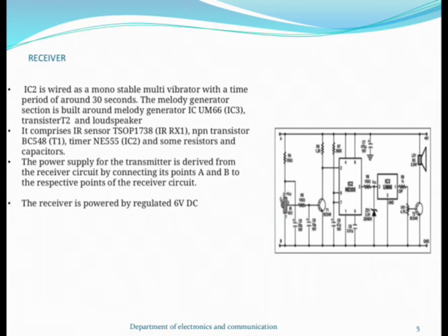Receiver. Another main role of an electronic watchdog is being performed by the receiver. IC2 is wired as a monostable multivibrator with a time period of around 30 seconds. That means the alarm sounds for about 30 seconds.